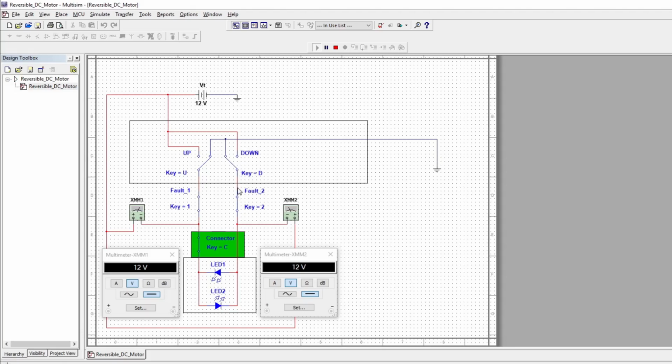You can check it for ground from the switch all the way through the switch and to its ground, and you can do that on both sides. But you haven't checked this other lead. So it could be this pole and this contact point here where it's connected to ground is fine, but maybe this positive one is burnt. And you would have to check this by the other means.